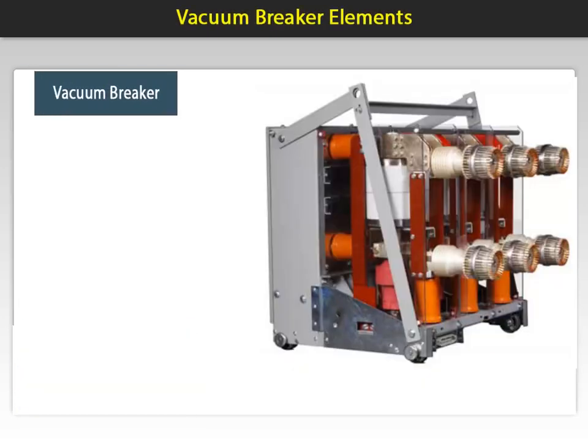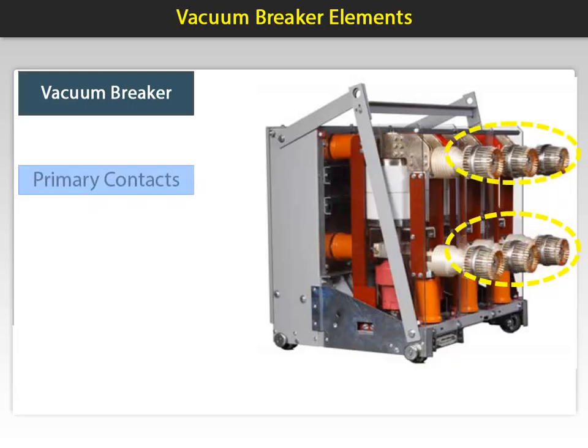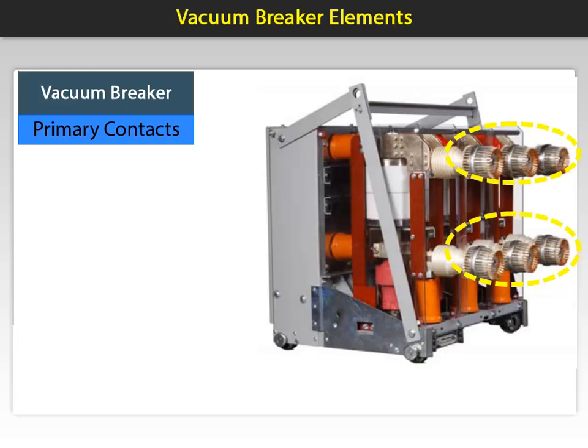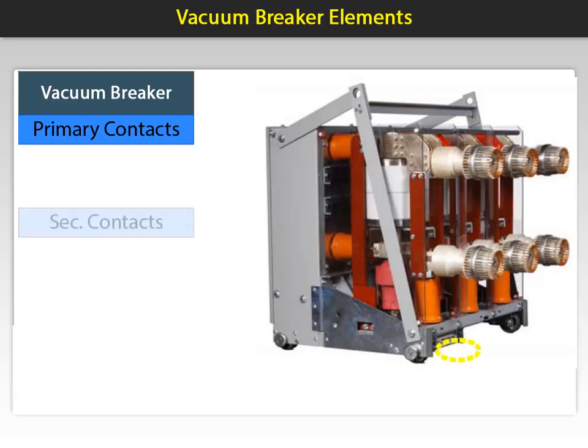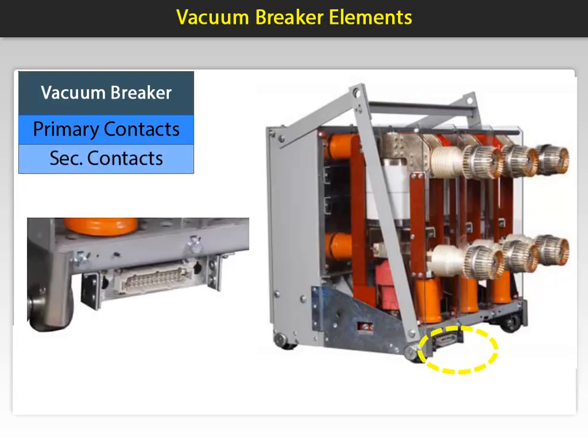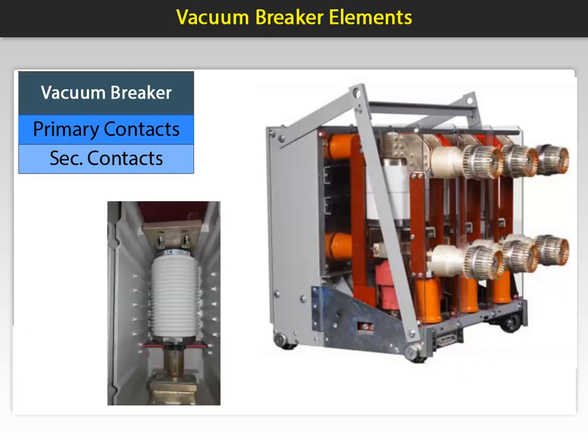Vacuum breakers are readily recognized by the distinct bottle or tube-like interrupter when facing the rear of the breaker. Much like the predecessor air circuit breaker, it has primary contacts that connect to the main and load bus. The secondary contacts located here plug into a matching secondary contact block in the switchgear cubicle. This is the vacuum interrupter itself.